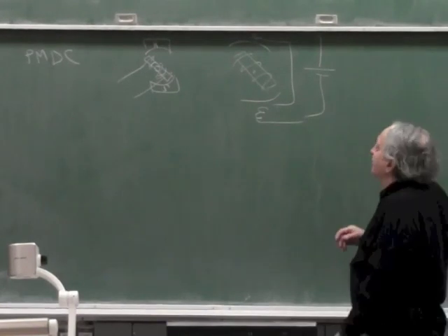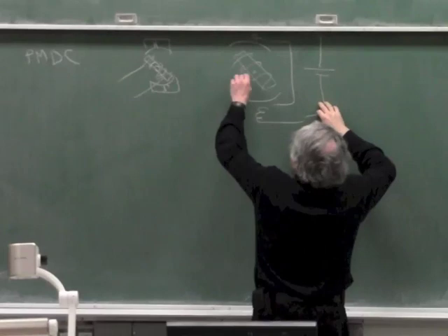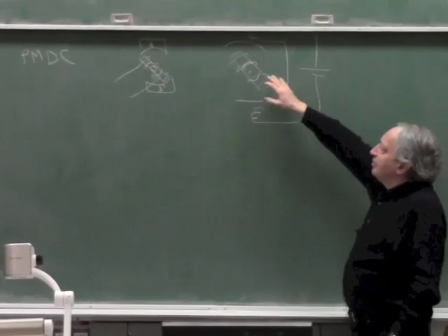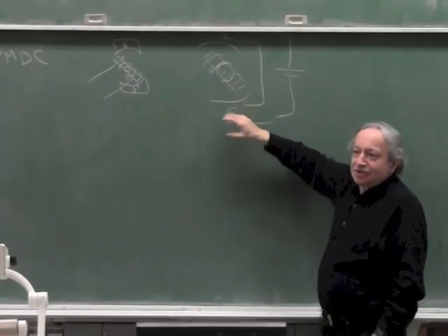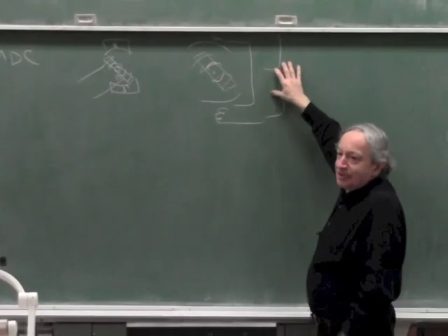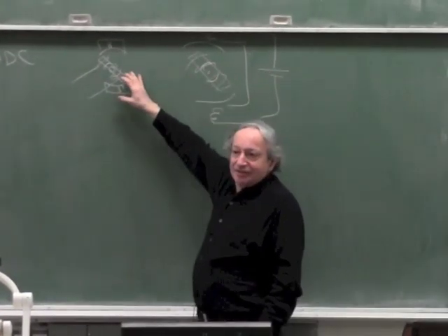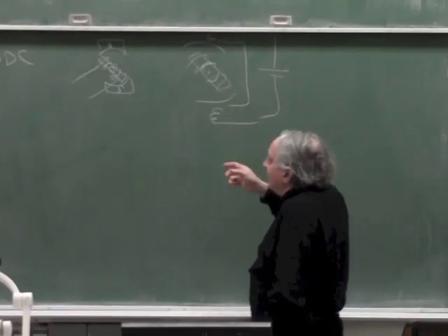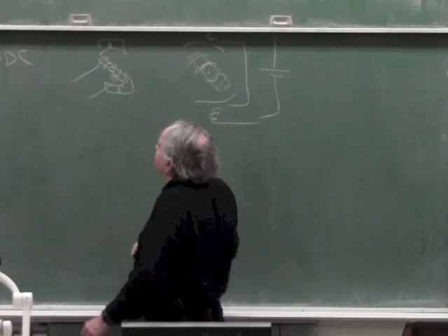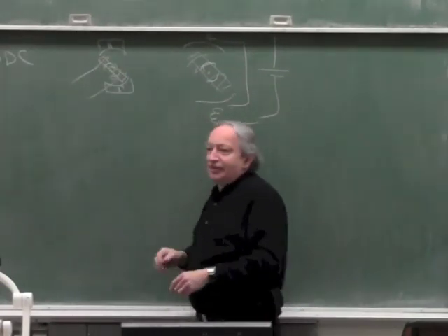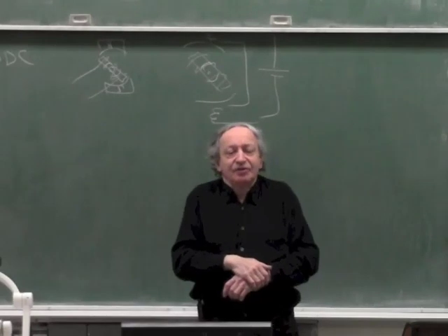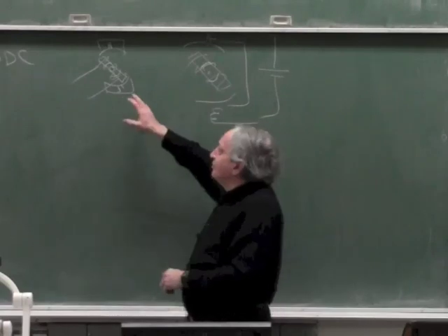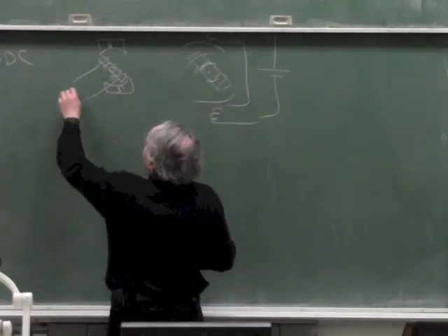Okay. Now, if this is the same battery which also powers the commutator, then there is a bit of a difference, because when you change the battery voltage, the field also changes. If this is a separate power supply, a separate battery, it's exactly like a permanent magnet. Good. So what characteristic would this motor have? When the motor starts turning, it's moving a conductor in the magnetic field. So every conductor in the magnetic field generates a voltage. So the equation of this motor is not as simple as if this is a voltage.